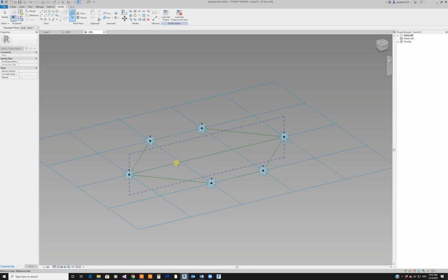I set it vertical, and this is set, and I just snap to the grid here, and I'm gonna go 90 degrees. 3000 is okay, and another one here. This one should snap to the older one. Just see the blue line. Yeah, now it tells me this 3000.